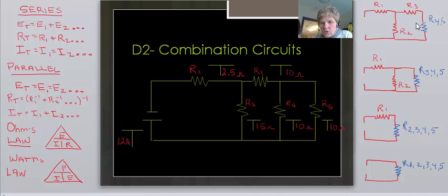What I've done is shown you some drawings on the right-hand side that show you how to reduce this circuit down to just the equivalent of one resistor so that you can find out what the R total is for this circuit. Notice that this circuit has a resistor R1 in series with everything up front, then a branch that runs down, R2, then another resistor that's in series with R4 and R5.